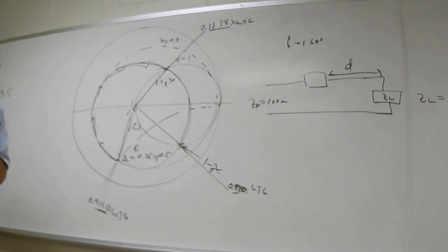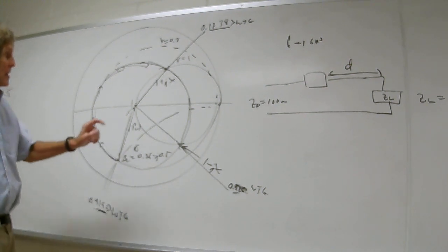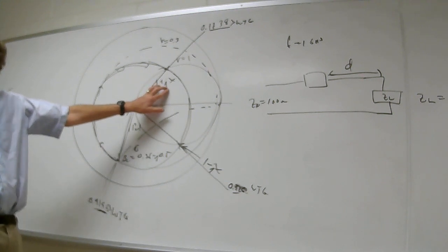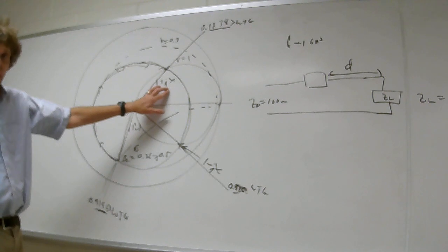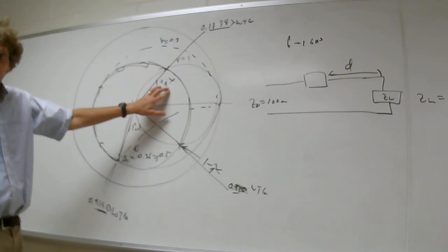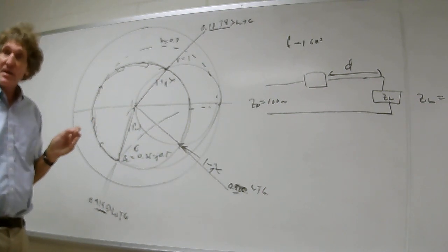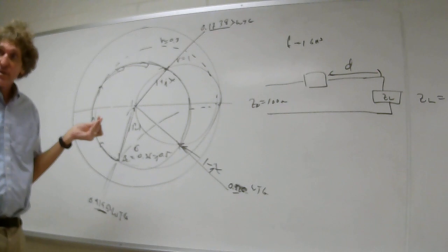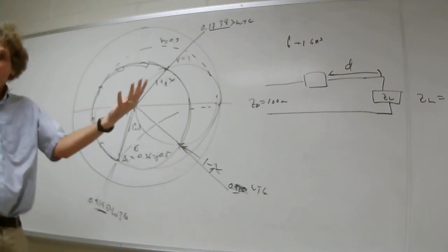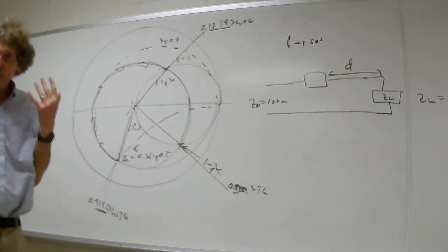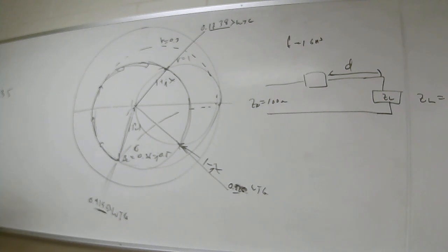Now look. Think about this. We're at 1 plus jx. That's normalized. If we take it out of normalization, it would be Z naught plus jZ naught times x, right? Now, here's the beautiful thing. If we can get rid of that jx Z naught, it's matched, isn't it? If you go into Z naught, there's nothing reflected. You all follow me on this? That's the idea.